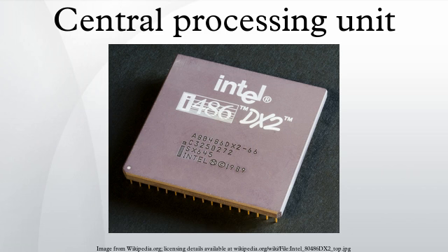Some types of instructions manipulate the program counter rather than directly produce result data. These are generally called jumps, and facilitate behavior like loops, conditional program execution, and functions in programs. Many instructions will also change the state of digits in a flags register. These flags can be used to influence how a program behaves, since they often indicate the outcome of various operations. For example, one type of compare instruction considers two values and sets a number in the flags register according to which one is greater.